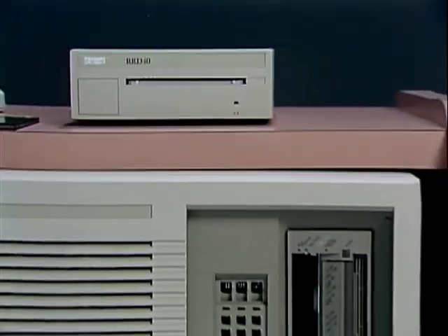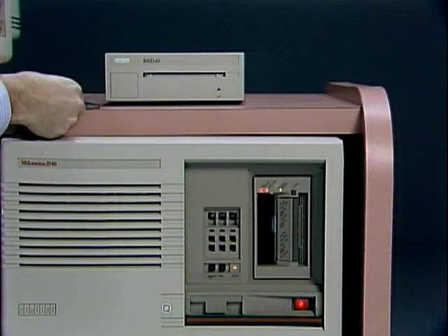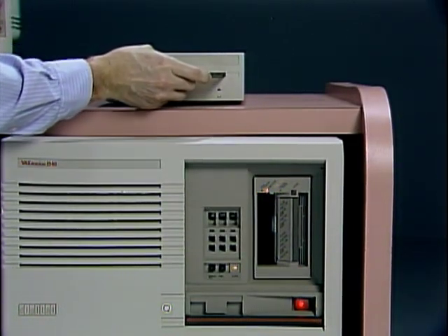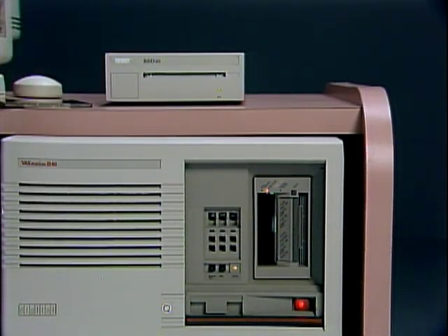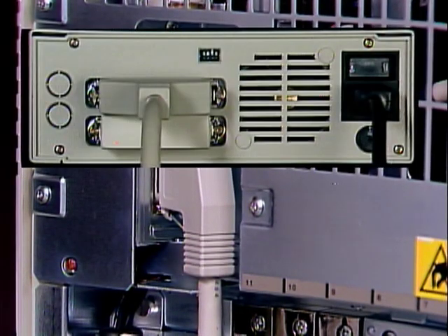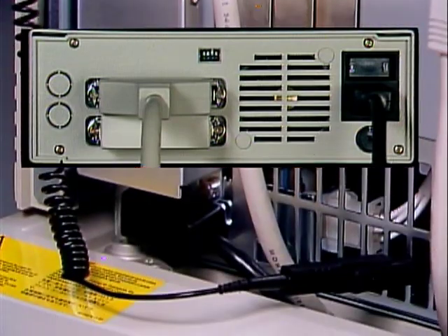The RRD40 CD-ROM disk drive is the only mass storage device that may be installed outside the system box. The VAXstation 3520-3540 workstation uses the SCSI interface to support a single tabletop RRD40. The data cable connects from the bulkhead on the mass storage cover to the back of the RRD40 drive. This cable is laced underneath the system cabinet.